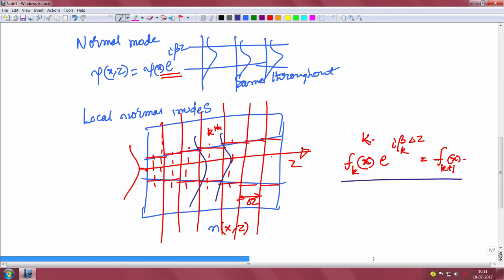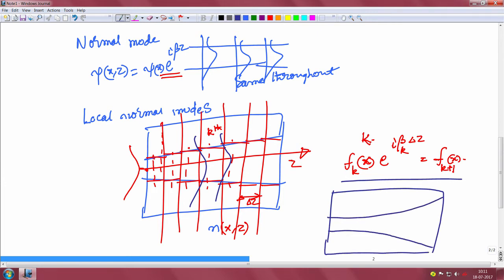field in each of these sections, and we can say that the mode field profile changes according to the propagation direction, and we can easily observe that it depends on the profile that you take. For example, I have chosen in this example a linear taper where the refractive index or the width of the waveguide varies uniformly. We can also think of refractive index profiles which need not vary uniformly. For example, we can have a taper which is like this, non-uniform taper. So, all these can be very useful to change the mode shape in an integrated optic circuit application.